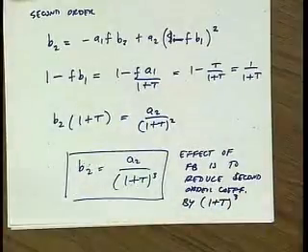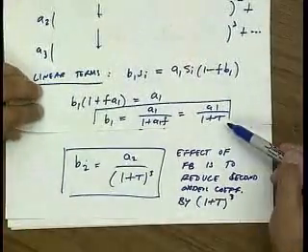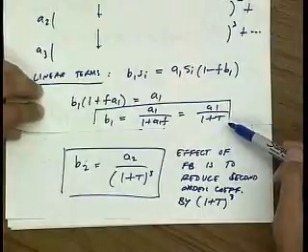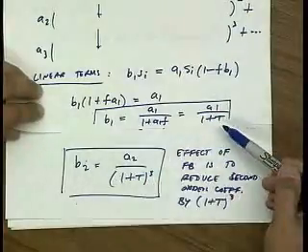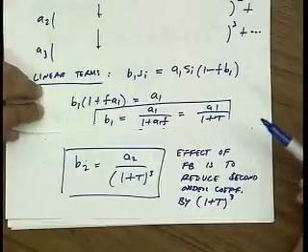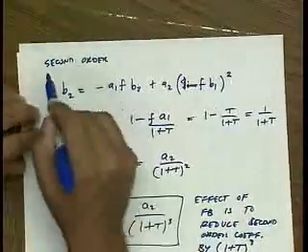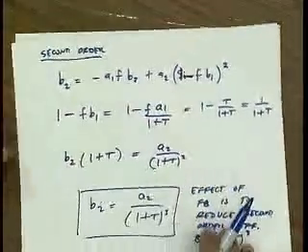Well, that's brilliant, because if we look at what the effect of feedback was on the linear gain, it only reduced the linear gain by 1 plus T. So if I still take the ratio of B2 over B1, I still have an improvement by loop gain squared. So that's really good. Okay. Well, what about the cubic term? Any questions up to here?